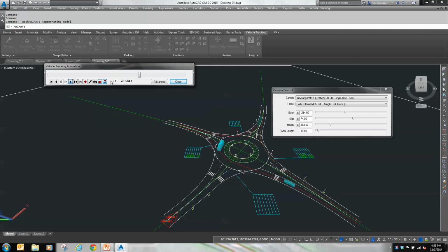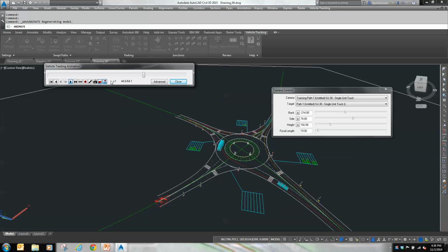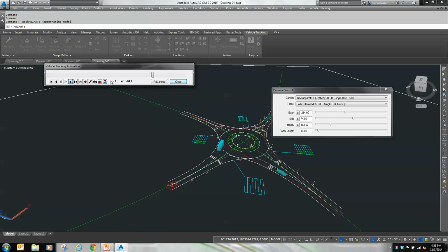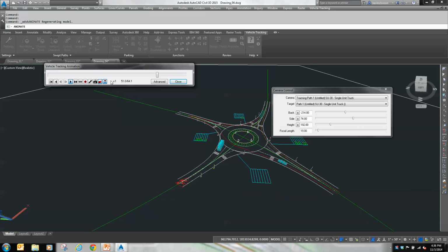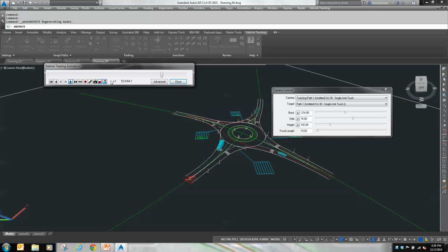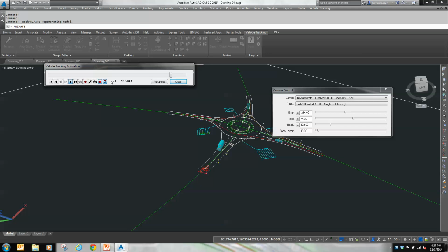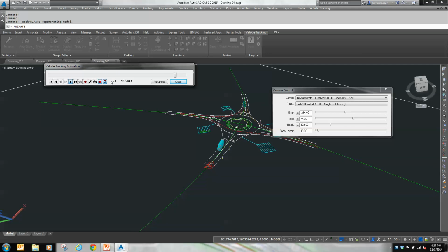I guess maybe for good measure, that corridor, even though it's a corridor, if I needed to turn that into a surface, it's just business as usual. Pick the corridor, go into your Civil 3D tools, and build a corridor surface. You know, and of course there'll have to be a few adjustments here and there, but really, that is it in a nutshell.